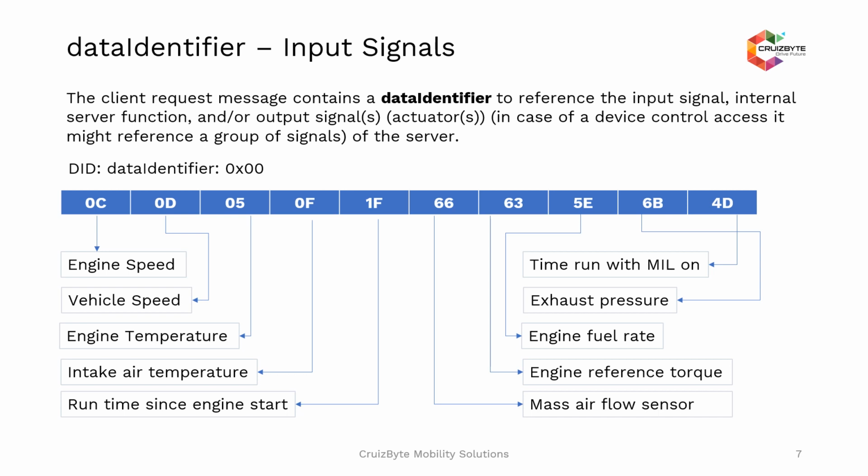So this is what is called a data identifier, and in this example the data identifier 0x00 consists of 10 signals. I can define one more data identifier called 0x01 with another 10 signals of different variables, and I can also have 0x03, 04, 05 and so on. Then I can have a different number of signals present in each of these DIDs.